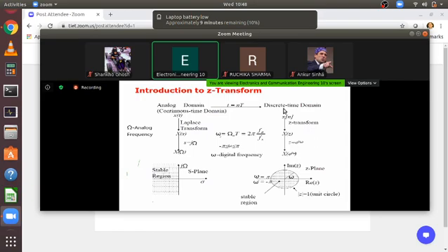And this fundamental period, please remember that this is very important. The fundamental period of the analog frequency exists from -infinity to infinity. But the fundamental period of the digital frequency is from -pi to pi, because beyond this, we saw in the sampling that the digital spectrum is actually the same as the analog spectrum, but the digital spectrum will repeat.